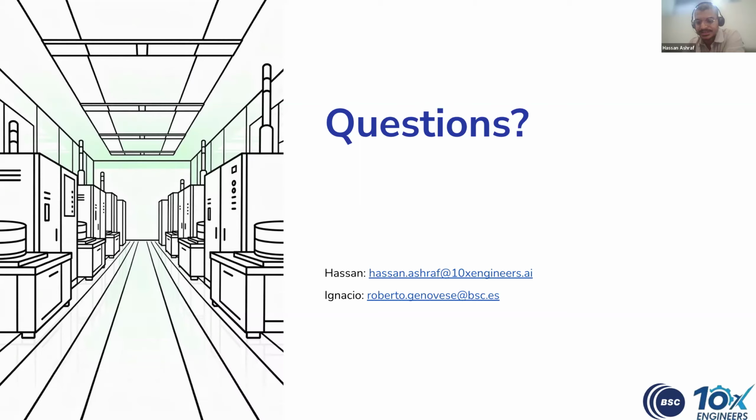I think the UVM that we mentioned is the implementation in the SystemVerilog library of UVM, which we usually run on Synopsys or Cadence tools or some other licensed tools. But for Cocotb, we do not need that SystemVerilog library. And the beauty, the use case of Cocotb, is that it's in Python, easy to understand, and it's open source, so we can actually get into the details of the source code as well. Yeah, exactly.